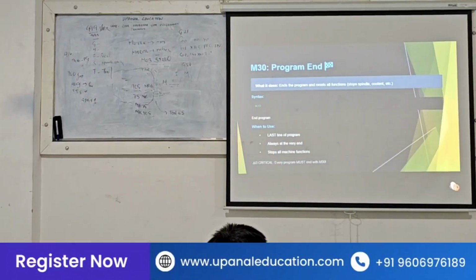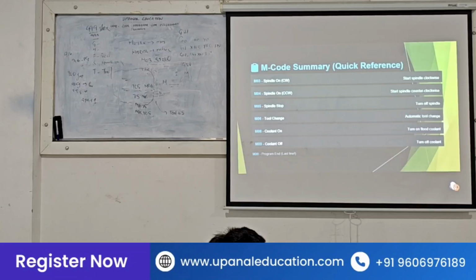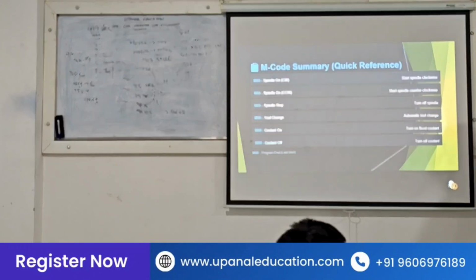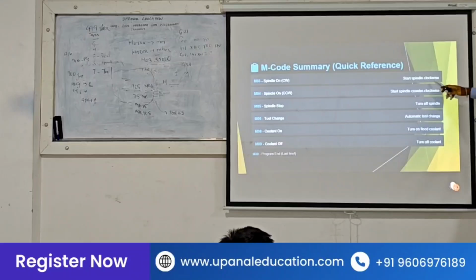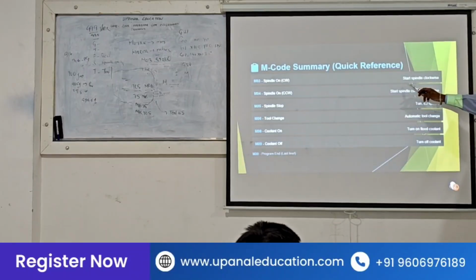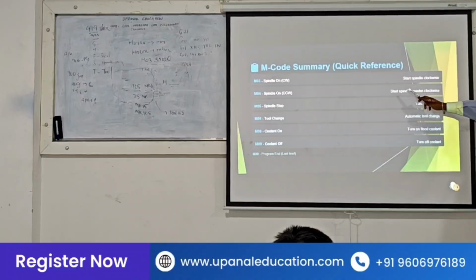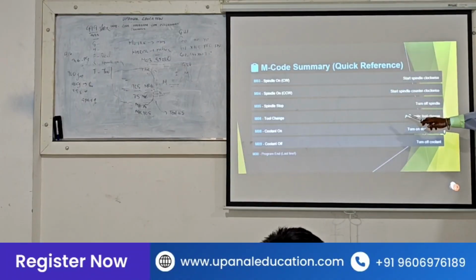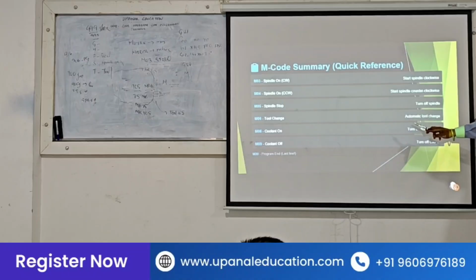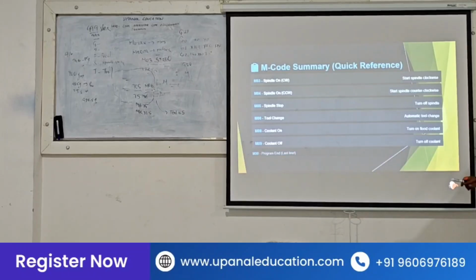Understood? Any doubts? So I told M03 is spindle on clockwise direction, M04 is counterclockwise direction, M05 is spindle stop, M06 is tool change, M08 is coolant on, M09 is coolant off, and M30 is program end.